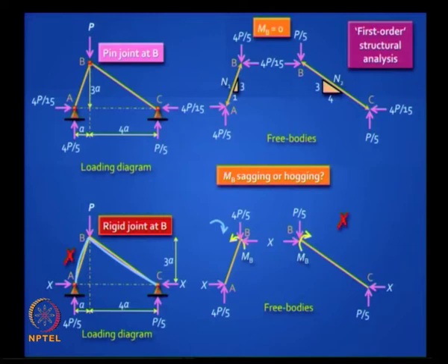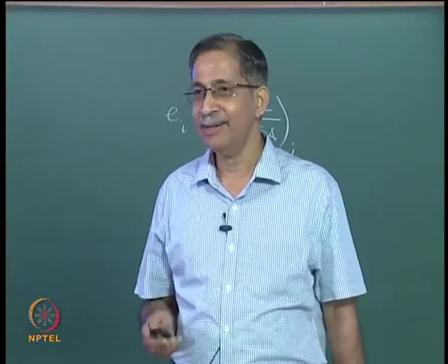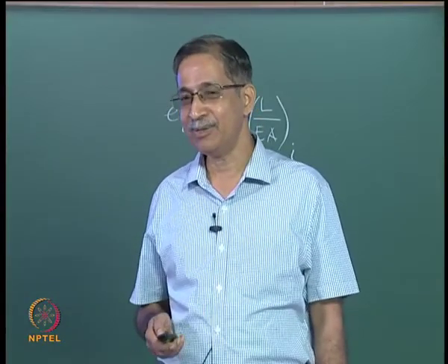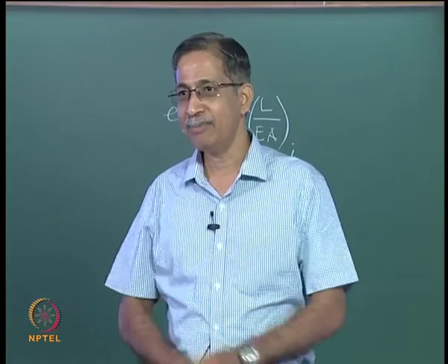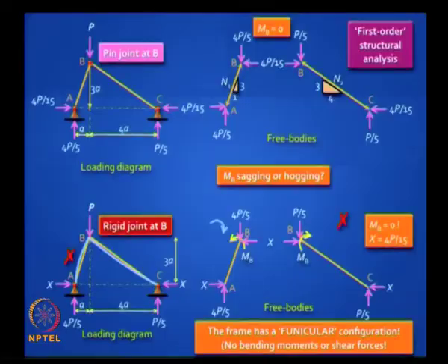There is another reason for this. Can you tell me why is there no bending moment? Perfect. This shape is funicular for that particular loading. And how do you recognize it's a funicular shape? When the concentrated load is acting at that point, the bending moment diagram is exactly